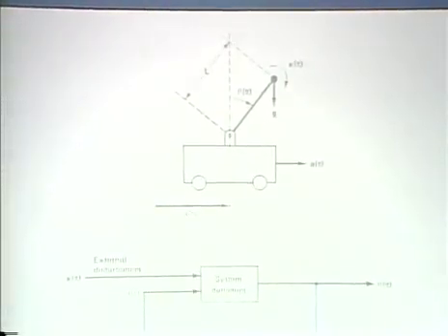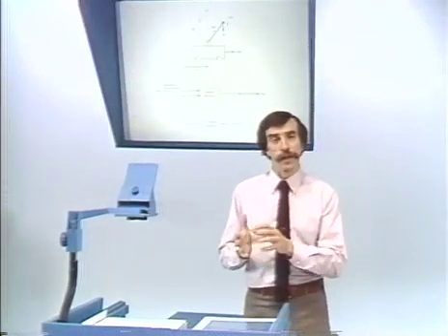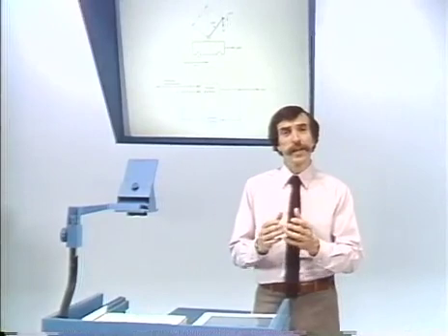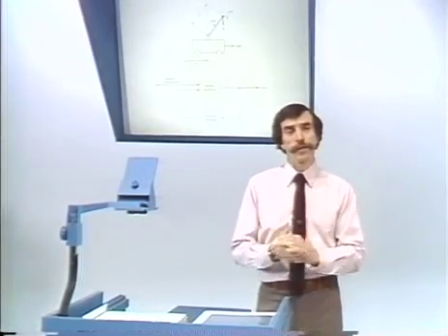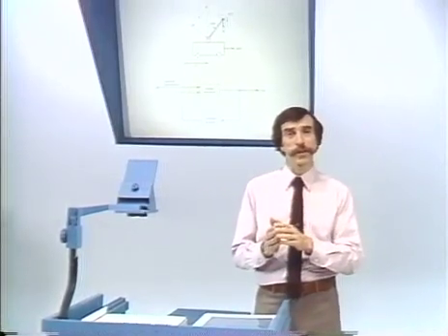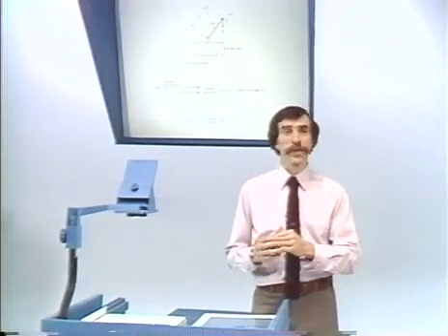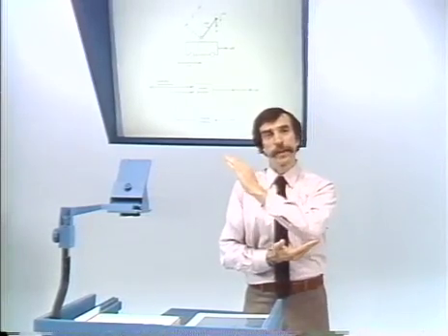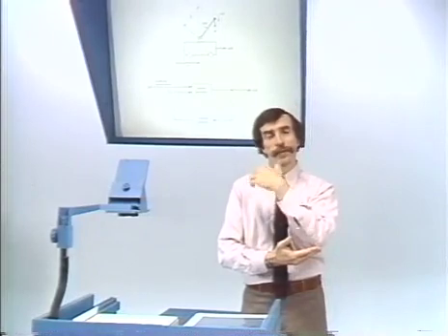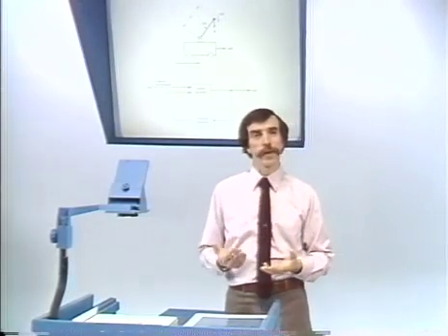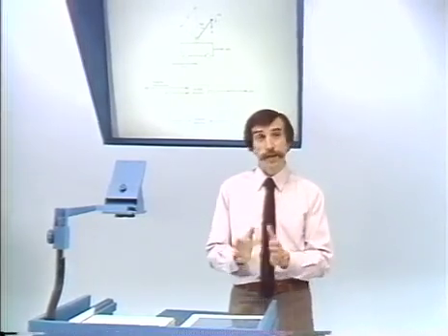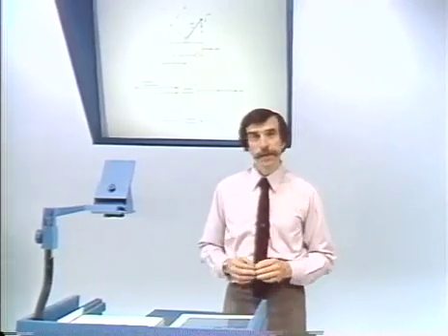In the next lecture, what I'd like to do is focus on a more detailed analysis of this. We'll see that the form of the feedback dynamics is important with regard to whether you can or can't stabilize the system. Interestingly enough, for this particular system, as we'll see in the next lecture, if you simply try to measure the angle and feed that back, you can't stabilize the system. What it requires is not only the angle, but some information about the rate of change of angle, but we'll see that in much more detail in the next lecture. Thank you.